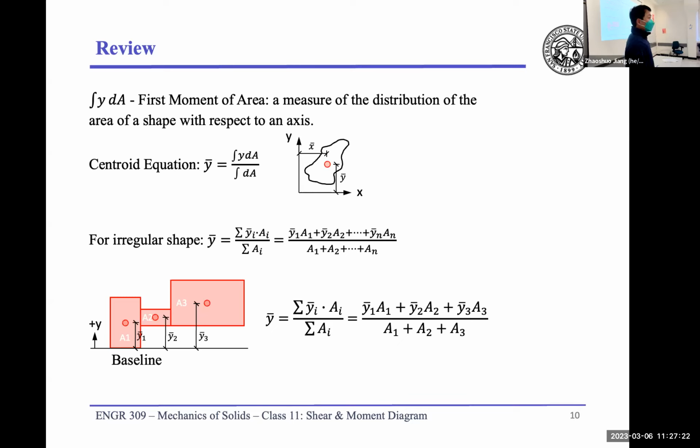It's going to be important because all those different irregular sections that we're going to see later on in this class, like triangular section, T section, etc., you always need to calculate the centroid first before you can calculate the moment of inertia. That's right. So the rectangular section is going to be your basic section because you already know where the centroid is.